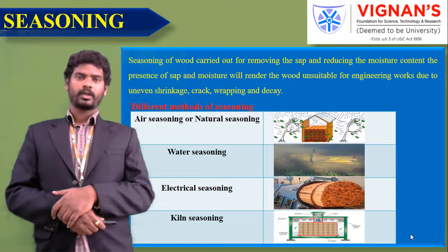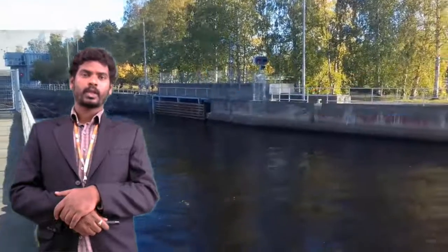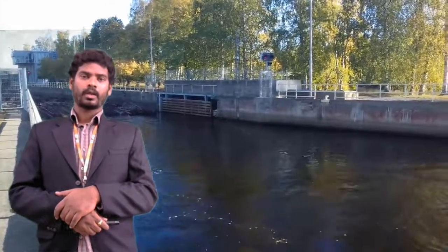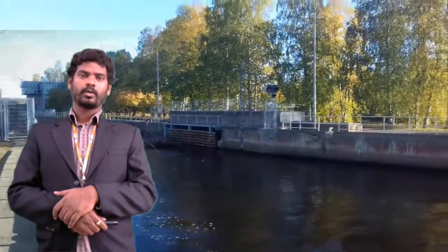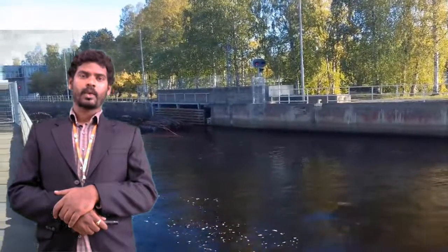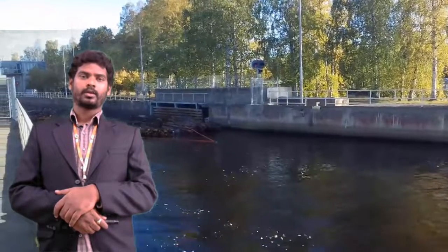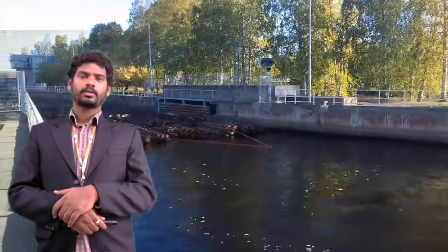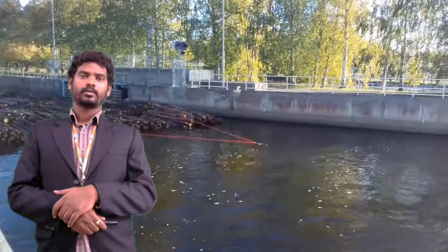The next one is water seasoning. In this method of seasoning, timber consists in keeping logs of wood completely immersed in a running stream of water, the longer end of the log being kept pointing upstream. By this process, the sap, sugar and gum, etc.